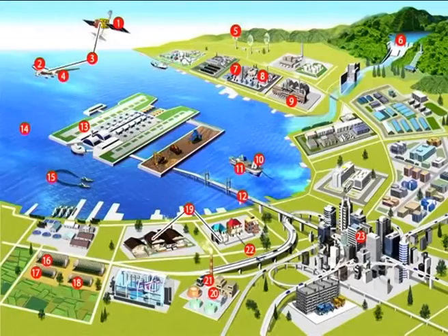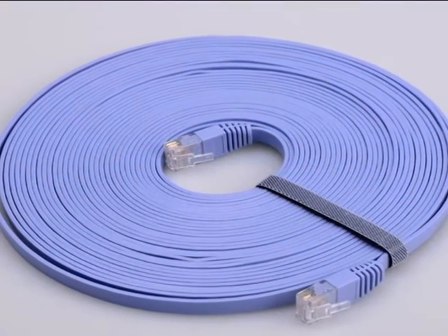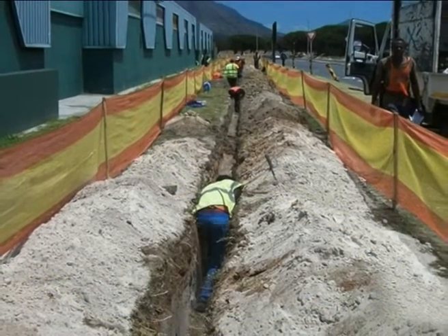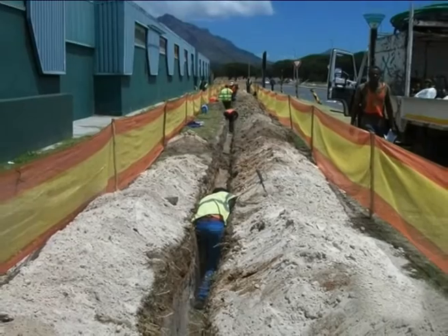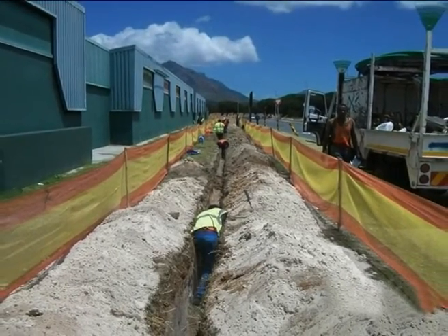Optical fiber communication has a number of advantages. They have greater capacity, due to which they can carry signals with higher bandwidth. They permit transmission over longer distances and require only a few repeaters. They are much lighter and thinner than copper cables of the same bandwidth. This means less space is needed in underground cabling ducts. These are also easy to install.